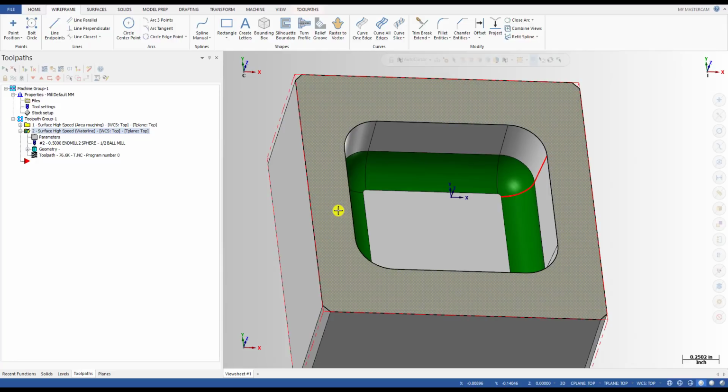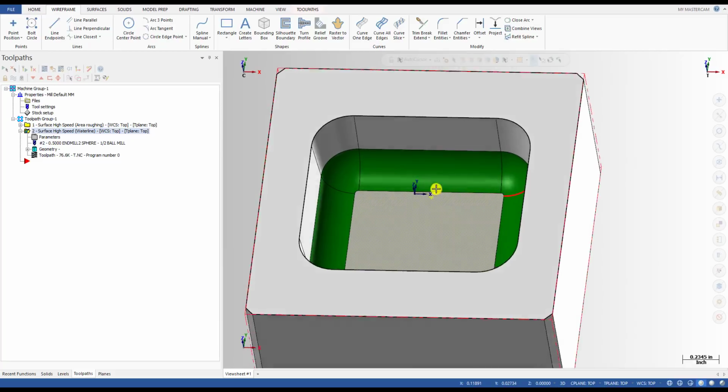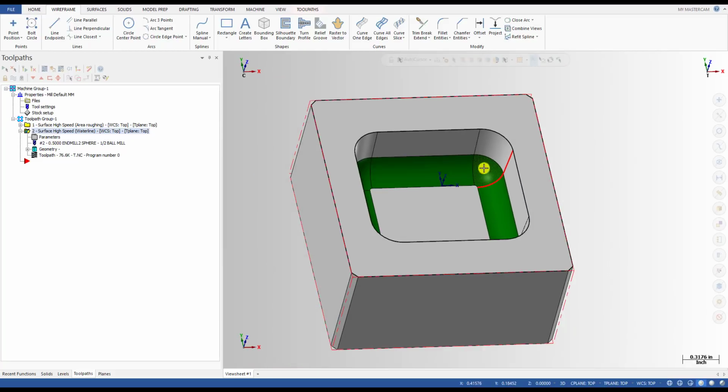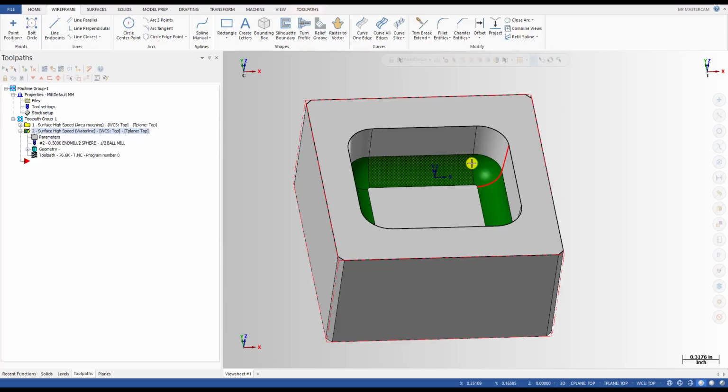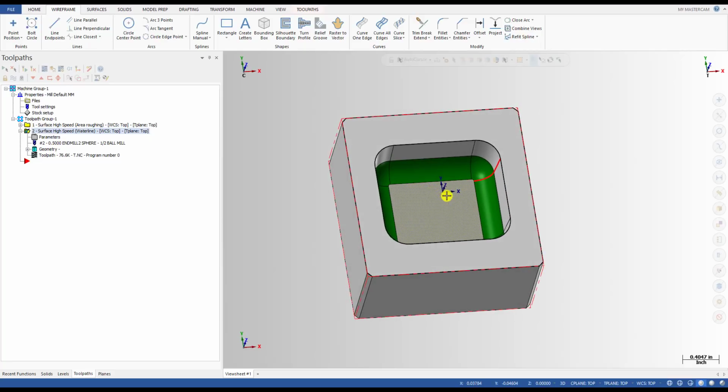If the design does not allow you to use a bigger tool, we have to run this radius with a smaller tool, for example a 3/8 ball mill, or even smaller like a 1/4 ball mill, so we can clean this corner. And if the design of the model allows us to use a bigger tool, in some cases that's not important, it's just for schematic looks, so we can use a bigger tool with no problem.